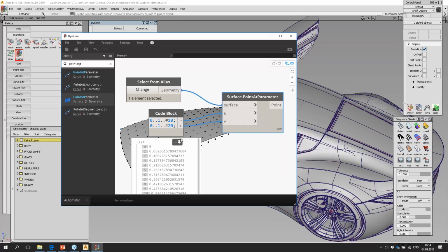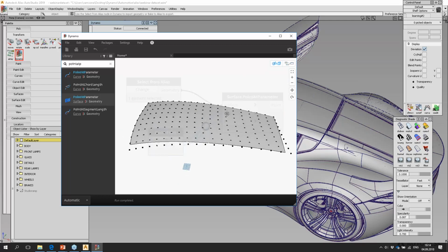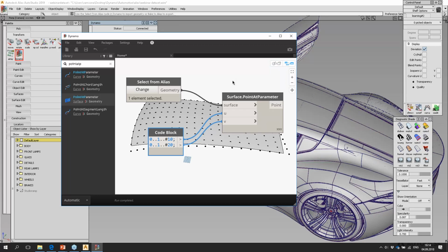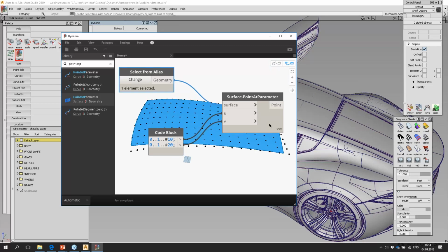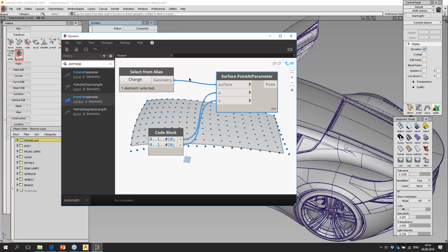Lacing cross product, okay? So what I'm doing now is I'm creating a logical flow, right? Because I'm selecting a surface and then I'm connecting this node with another node, which is actually putting points on that surface. So in Dynamo, I can create very complicated, in terms of sophistication, let's put it in these words, flows of data, which will always be parametric, right?